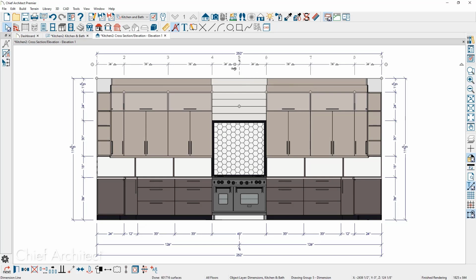You can also toggle a particular dimension string. You see the highlight with the red handles on it. There is a remove and add centerline indicator in your lower edit menu. I'm going to just remove that centerline dimension string since the centerline dimension string at the bottom is picking it up and they're both exactly centered. I think I've got enough information on the top dimension strings.